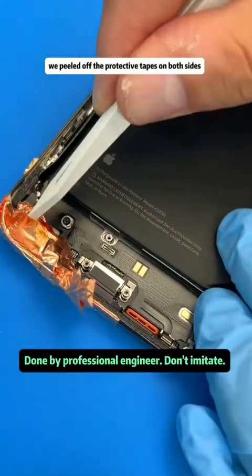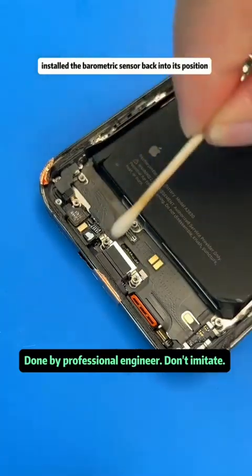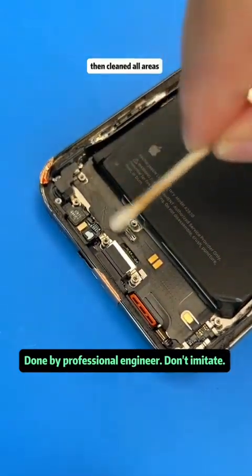We peeled off the protective tapes on both sides, wiped off the remaining corrosion agents, installed the barometric sensor back into its position, then cleaned all areas.